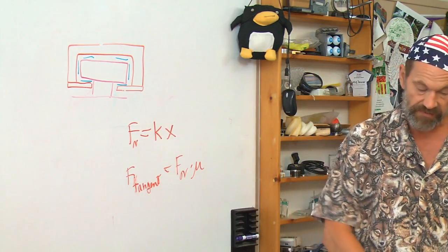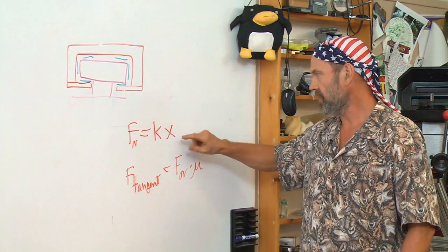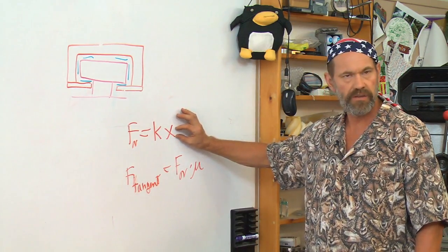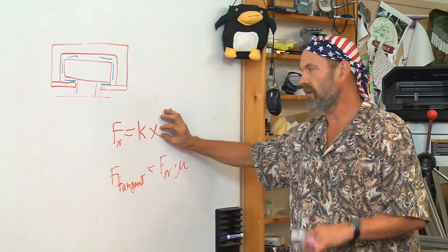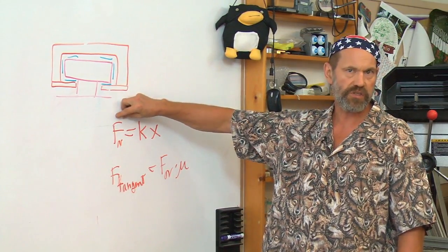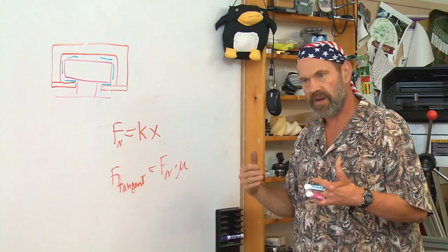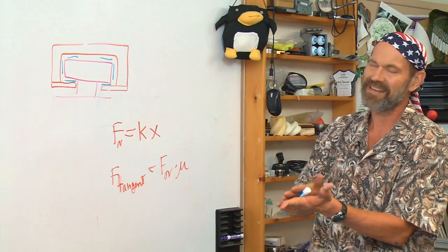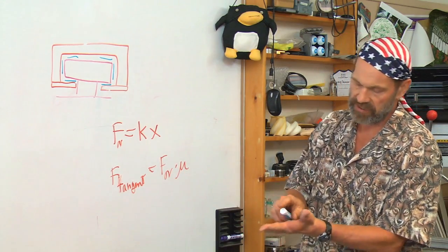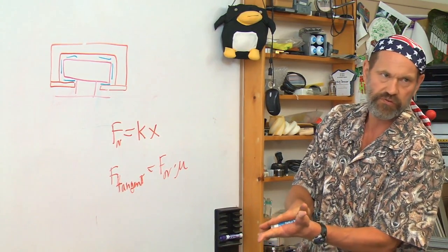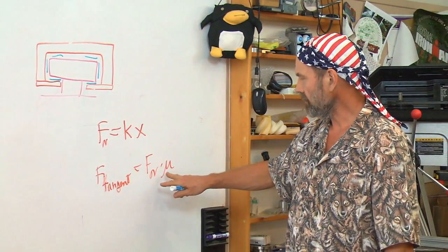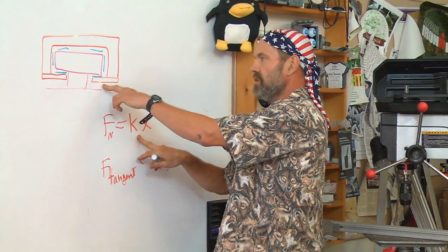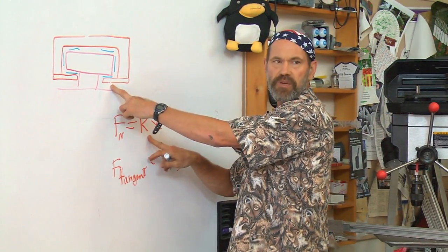So you've got to be very careful that if your bearing is very stiff and you have a small motion deflecting the bearing, it can cause huge normal forces. In a rolling element bearing, you may not feel it because it's rolling element at such low friction. Whereas a sliding bearing, you'll know it very quickly. This K here you can control with the shape of the structure and how you preload it.